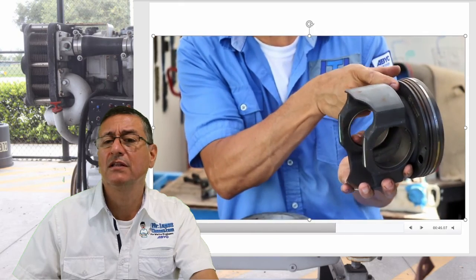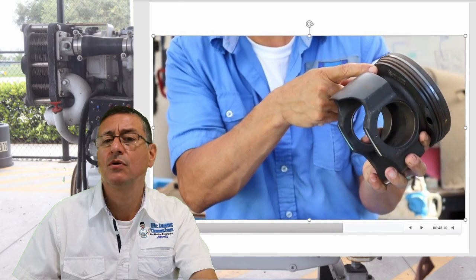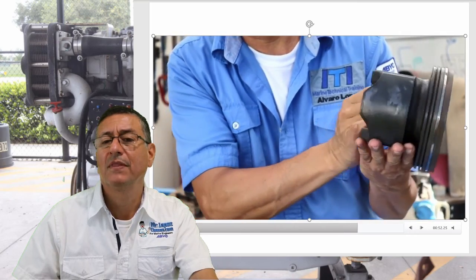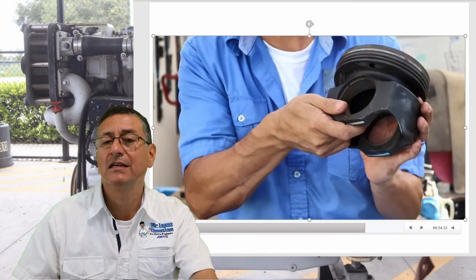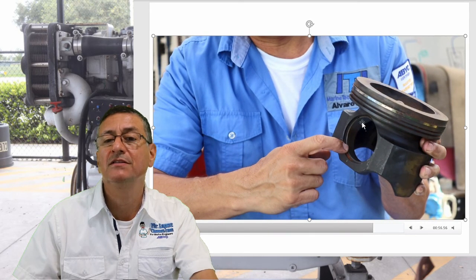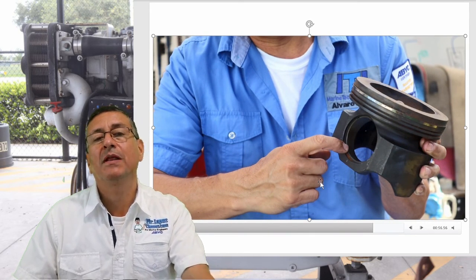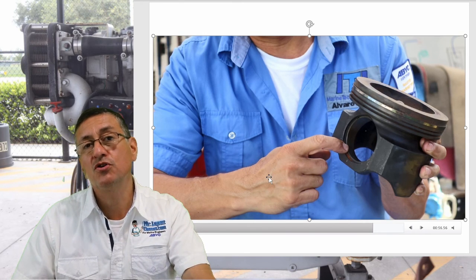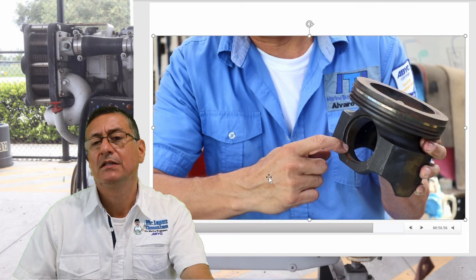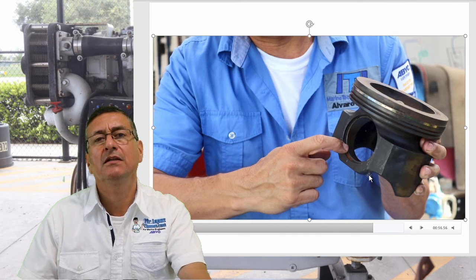Those are the grooves. The third one has those drills to communicate, to return the oil to the bottom. Yeah, that's completely fabricated in steel, and those are the piston rings, the plain bearings for the pin. That plain bearing is bronze with phosphorus, you remember? Those are the plain bearings. This piston is fabricated in steel.